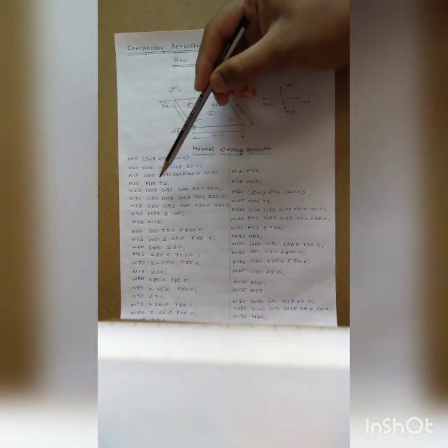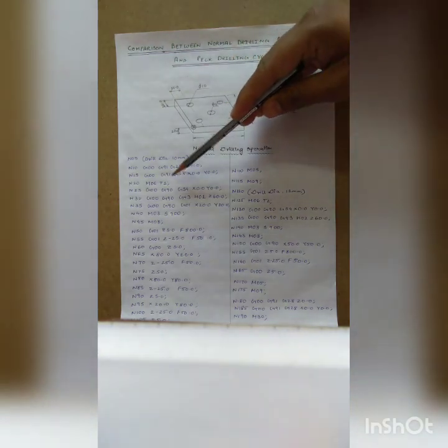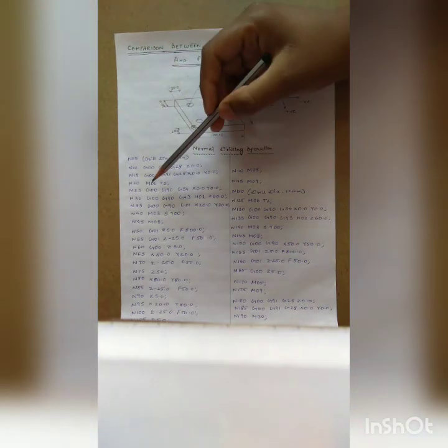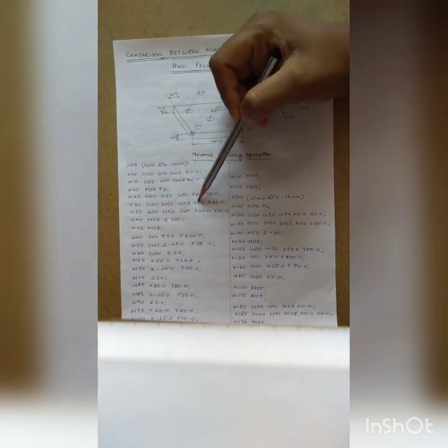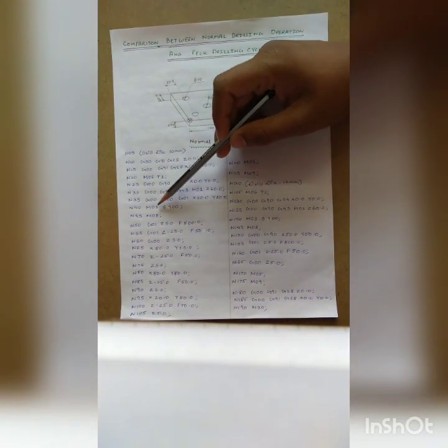These two lines are very important at the starting of the program. So M06 T1, that is tool change, and T1 means tool number 1. This is the work offset saved at G54. Now G00, G90, G43, H01, Z60. This is the tool offset for tool number 1, and Z60 means the tool is kept 60 mm above the workpiece. So it is the tool offset.